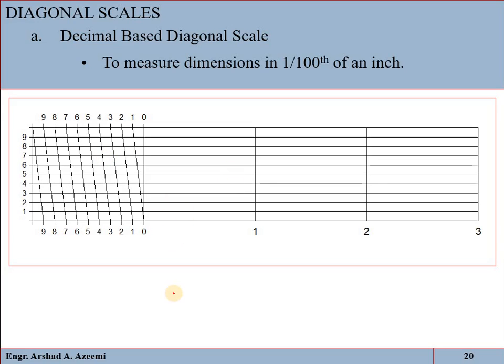And that is the diagonal scale which we have also drawn in the previous slides. If you draw it with actual dimensions with the help of the drawing instrument, the diagonal scale will look like this one. Now this is 1.37. Up to here that is 1 inch, 1.1, 1.2, 1.3. Then in this line go 1.31, 1.32, 1.33, 1.34, 1.35, 1.36, 1.37.